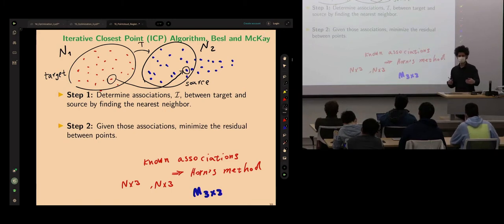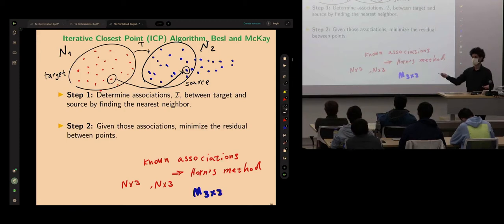At the step where we associate these points, we search for nearest neighbors, given the current transformation guess. For every point in the target, I will try to find one association, the closest point. At that iteration, that will lead to having the exact same number of points in the 2 clouds, because I ignore the rest. I only keep the associated points.